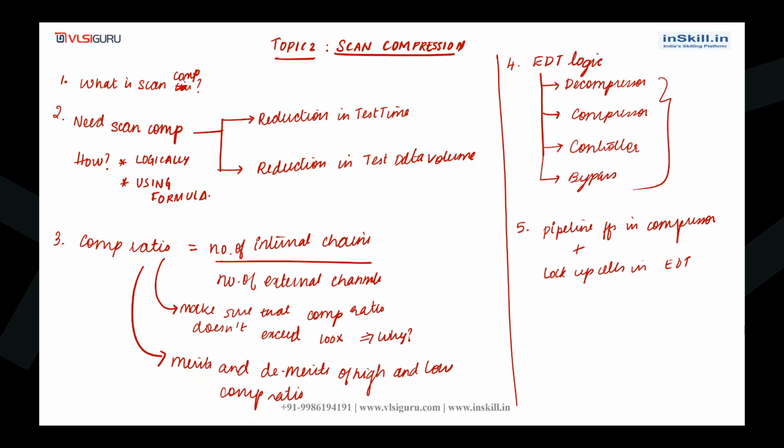Whenever you go for scan compression, if you are using Mentor Graphics tools, you will be adding a logic called EDT logic, which is embedded deterministic test. Inside the EDT logic you have components like the decompressor, compressor, controller, and bypass logic. We will understand the structure and functionality of each component and the role each plays in scan compression.